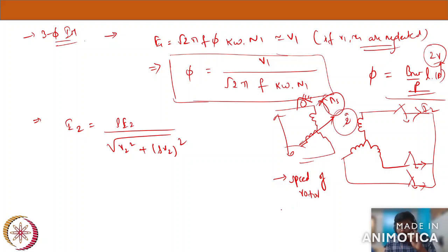So no, in the last class we discussed that both stator field and rotor field, we are not talking about rotor mechanical speed, it's the field speed. The speed of rotor and stator field is always ns with respect to a stationary observer. So here a stationary observer observing the speed of stator field and also the rotor field will notice that both fields are rotating with the speed of ns, but this is not a mechanical speed of rotor. If we talk about the mechanical speed, it is nr, but the field produced by the rotor and stator always rotates with the same speed, that is ns.